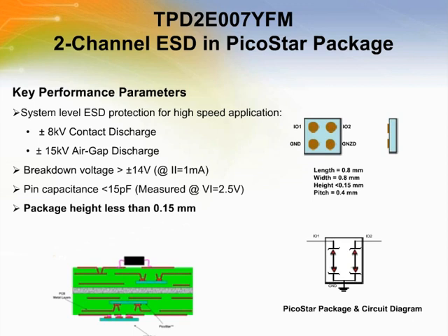This device is an application-specific integrated part designed to offer system-level ESD solutions for a wide range of portable and industrial applications. The back-to-back diode array allows AC coupled or negative going data transmission for audio interface, LVDS, RS-485, RS-232, etc. without compromising signal integrity.